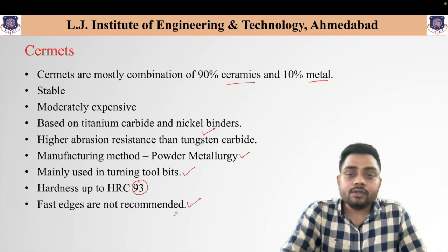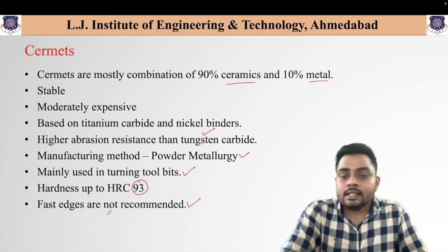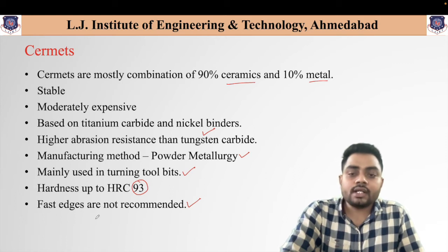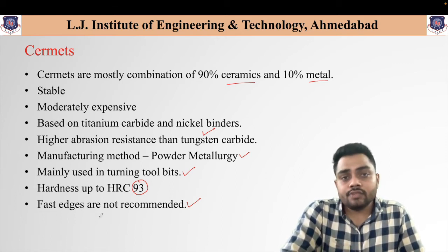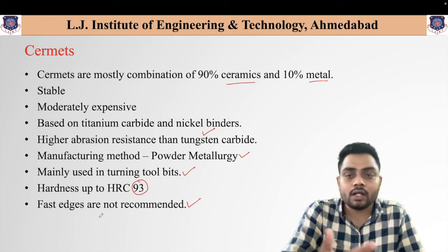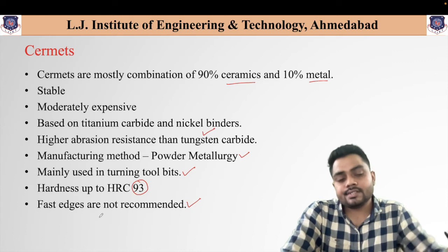For this cermet tool, the major limitation is that sharp edges are not recommended. Sharp edges cannot be used with the cermets because these are brittle in nature and they may get broken at higher speed operations.